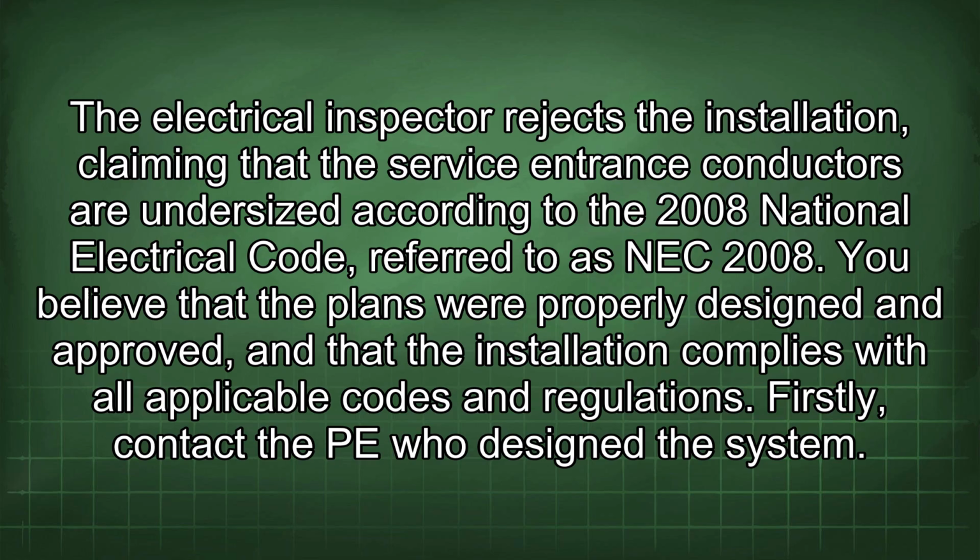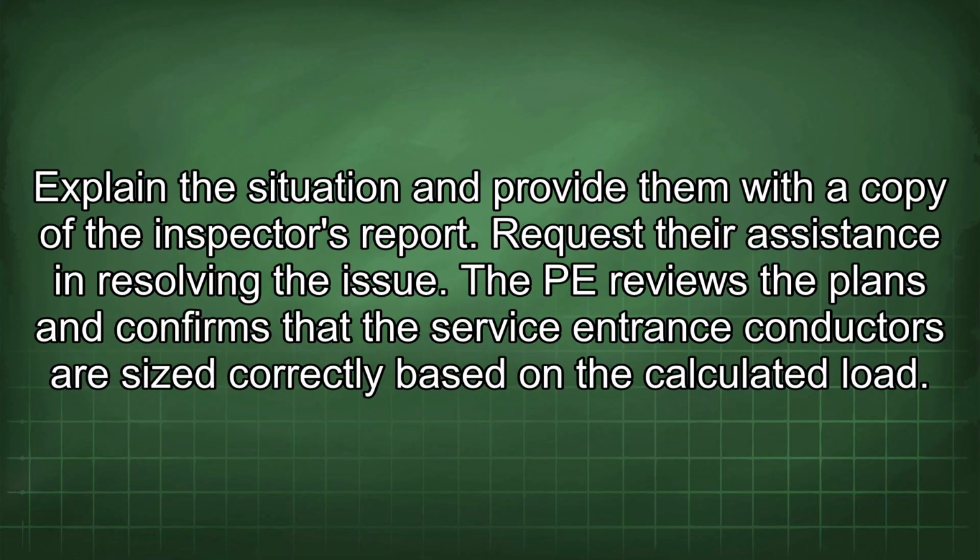You believe that the plans were properly designed and approved, and that the installation complies with all applicable codes and regulations. Firstly, contact the PE who designed the system. Explain the situation and provide them with a copy of the inspector's report. Request their assistance in resolving the issue. The PE reviews the plans and confirms that the service entrance conductors are sized correctly based on the calculated load.